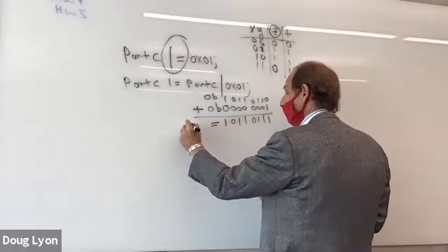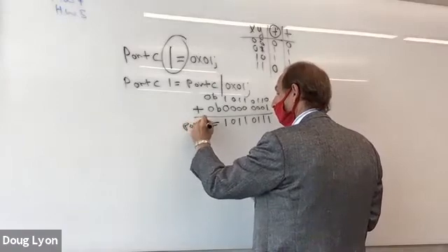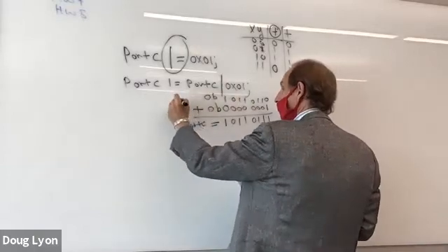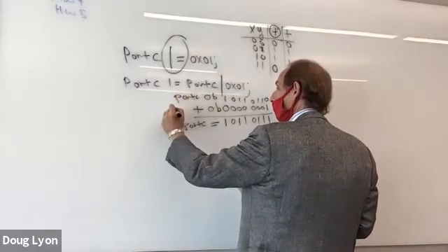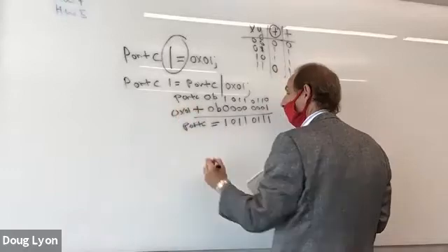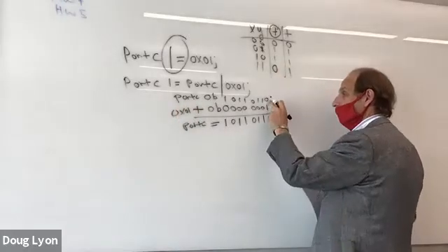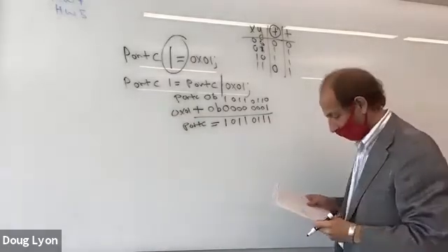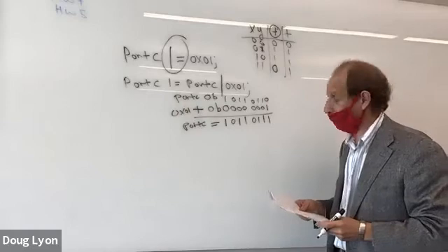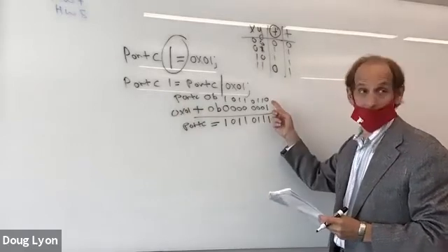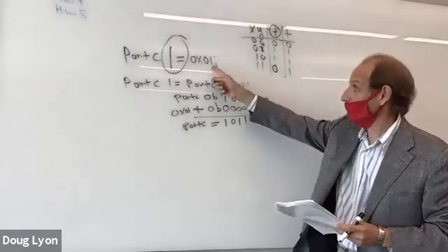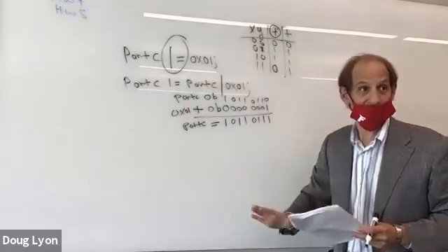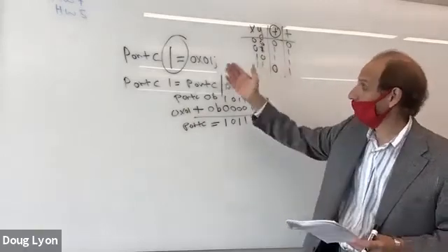And now we're going to set it equal to port C. What has changed? If this was port C to begin with, and this is 0x01, what did we do? We set the least significant bit. That's what we did. So what does this do? It sets bit number 0. That's a basic bit operation. You want to set bit 0, this does that.